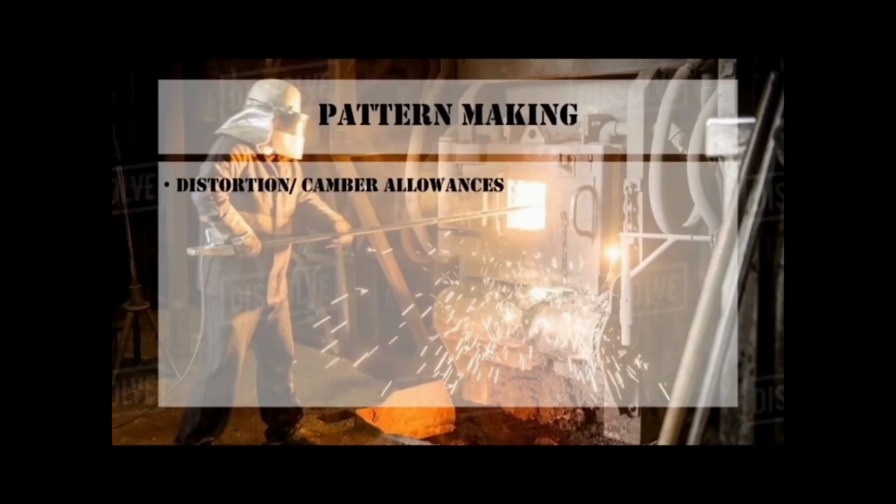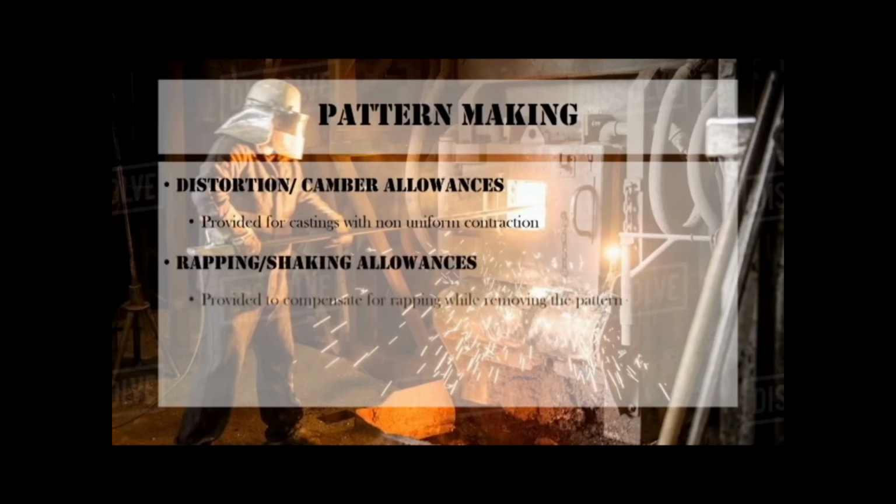Camber allowance. Castings with non-uniform contraction are to be provided with a camber or distortion allowance. Rapping allowance. Before removing the pattern, it is rapped in the mold. To compensate this, rapping or shaking allowance is given.